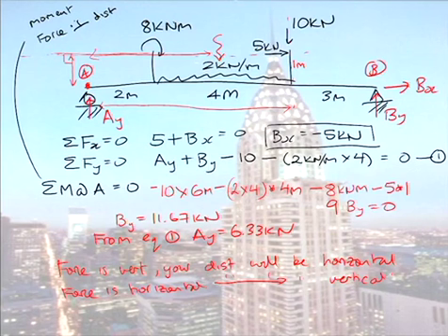An applied moment, it doesn't matter where that 8 kilonewton was applied. I could have actually applied it up here at the other upstand. I could have applied it here. It doesn't matter, it's already a moment. So you might say, well, why doesn't it matter where the moment is? When I spin my pen here, I can hold it here at the tip and it spins round. I could then hold it at the other end and spin it and it spins round the same way. So it doesn't matter where the moment is actually applied, it causes the same reactive forces.